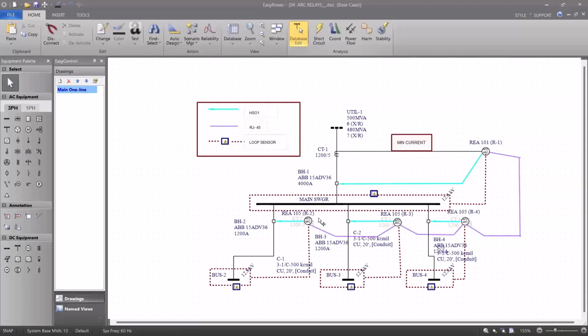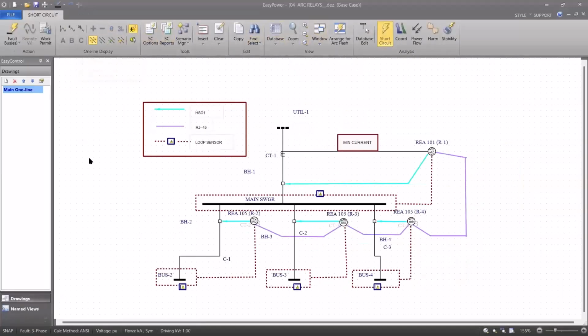So in this particular case, my zone of selection includes the downstream switchgear. I have a light sensor there, a light sensor on my main switchgear, and then repeaters that relay that location's arc, or the sensor picks up the location of the arc and will activate whichever breaker is least restrictive. And when I say that, when we go to short circuit focus and look at incident energy and fault this bus, we can see we have a protection of 3 calories,